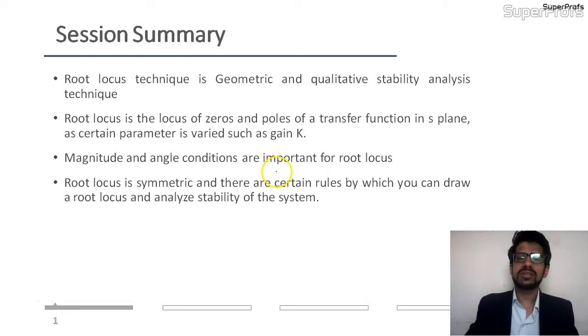We saw that once the system goes past the j omega axis, the system becomes unstable. Also, the root locus part which lies far on the left hand side of the j omega axis is more stable than the part of the system which lies near the j omega axis on the left.